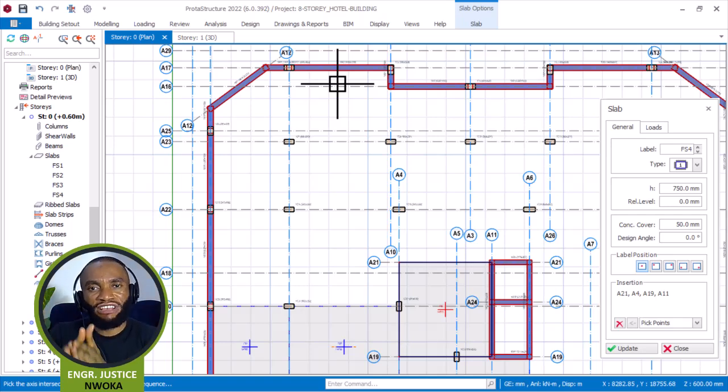But if you have several panels on the bay, you will see that at the portion where the columns are, knowing that the columns are going to have punching shear issues, we have different sizes of reinforcement and different spacing, or the slab might have the same reinforcement but different spacing, because coming close to the column there is much more stress and pressure from the column load than going far away from the column. Okay, that's fine, which you will see in this design.